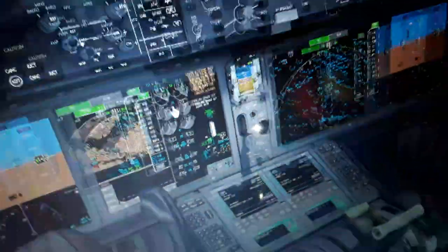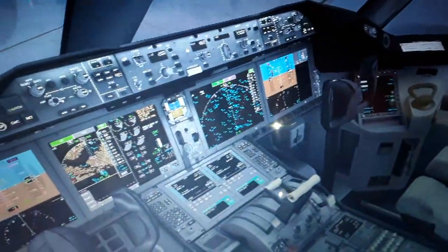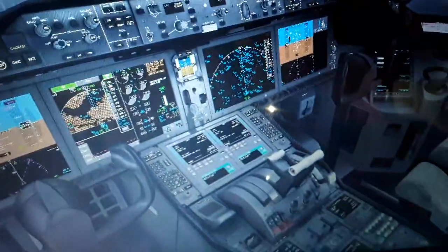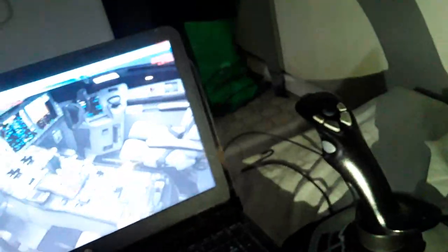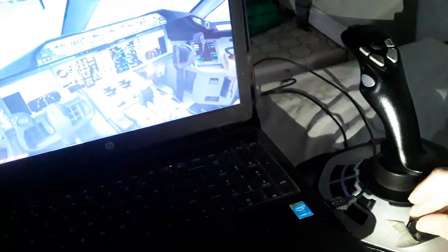So I will show you also, as I told you, the autopilot flight director system panel, the displays, the thrust levers over here. So when we use the flight controls, as I told you, I will complete now the flight controls. We have also the yoke, climb and descent, with the control column for the elevator, ailerons and spoilers left and right, using control wheel or the rudder pedals. We have also the flaps and the slats, the horizontal trim stabilizer, the thrust levers. Also you can see here the nose wheel steering and the thrust levers. You can see we can move the thrust levers like this.